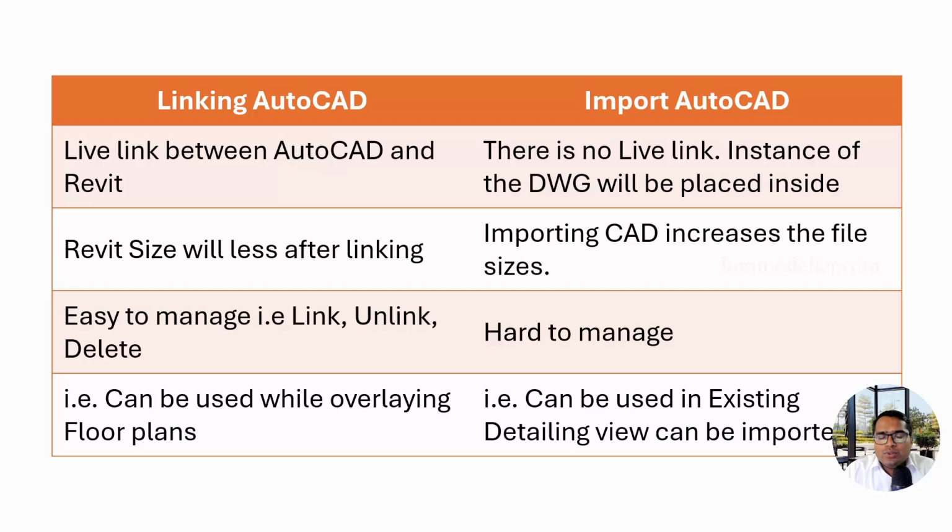When it is imported, you know that it's going to be a breaking link, and it is exactly like copying and pasting the element to the model. So it doesn't have a link, and you don't have an update once the model is updated from the consultant. Say if they are giving another release or a revision of the model or drawing, you will not be able to get the updated details. So you may have to delete the import and relink it.